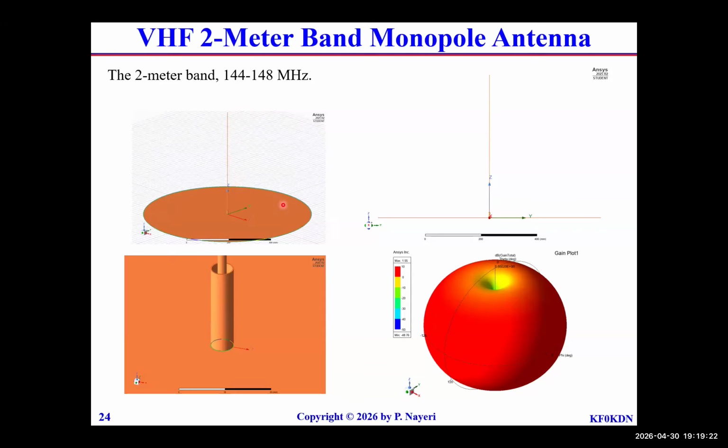I believe you plan to use a nitinol wire for your experiments, and I don't know what diameter you're using there. As far as I know, in the HFSS material library, I couldn't find nitinol, but its conductivity is high. Its resistivity was pretty good. So from the perspective of determining your dimension, you really just need to tune the length. You don't have to worry about the material. You can just use copper. 1 millimeter diameter. Okay. I'm using 1 millimeter radius, if I'm not mistaken. But you have the HFSS file, so you can fix that.